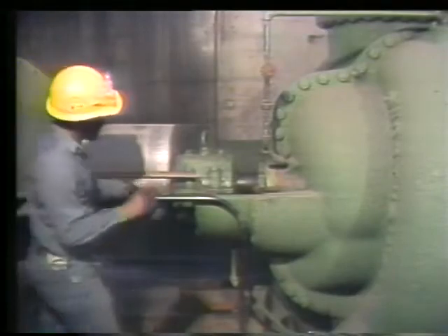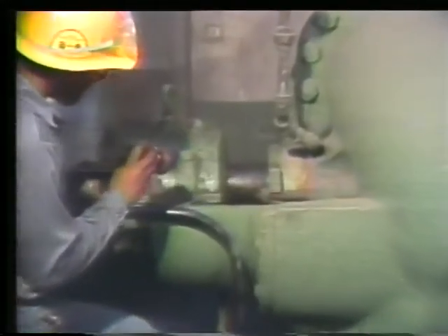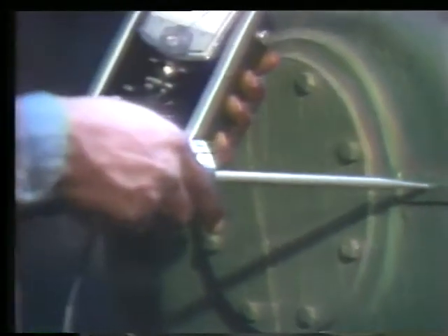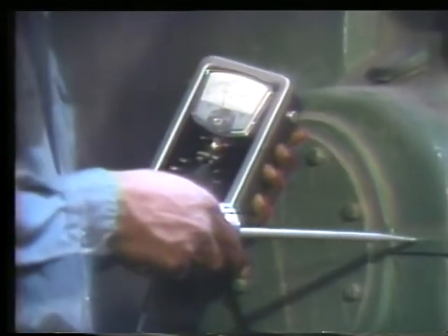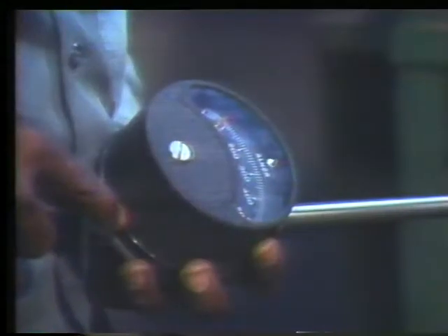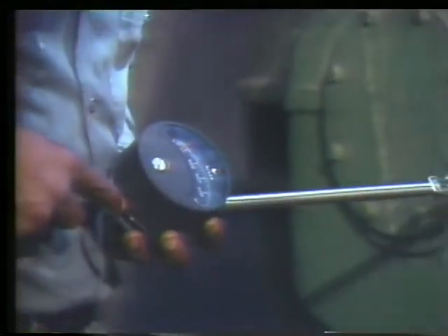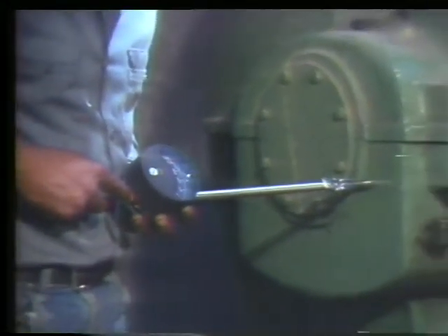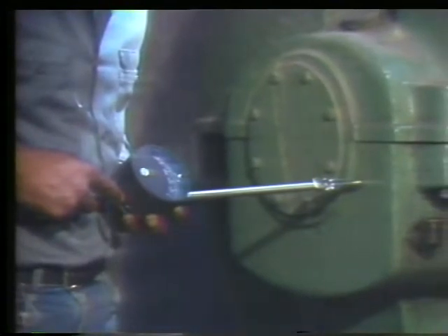You should also look for unusual movement of the shaft or vibration of the motor. Some motors have instruments to measure temperature and vibration permanently installed in them. You can easily take a reading for these motors. For other motors, though, you'll have to use a vibration meter to measure the vibration of the motor, and a contact pyrometer to measure its temperature. In either case, readings should be compared with previous readings taken under the same conditions to see if a trend is developing.